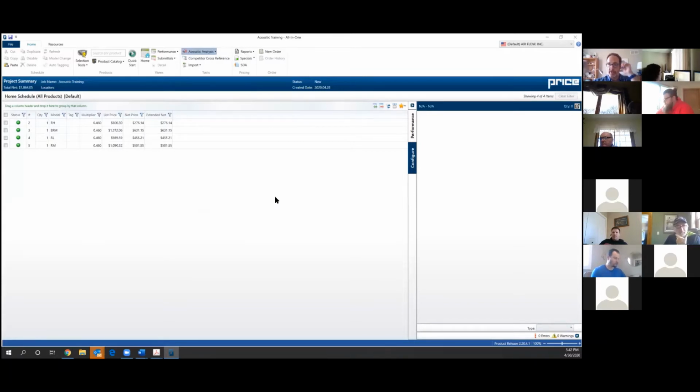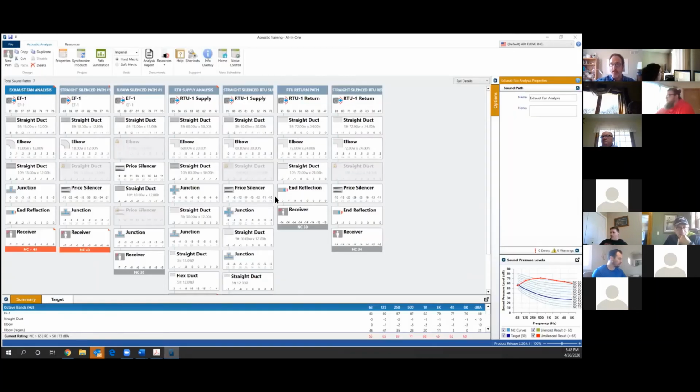And in order to make sure I don't bomb this presentation, I put the examples in, and I want to walk through those with you pretty slowly. So this first one, with COVID going on, we're going to see some more applications for isolation rooms. We're going to have low CFM, high static fans as we're pulling through HEPA filters, that kind of thing.